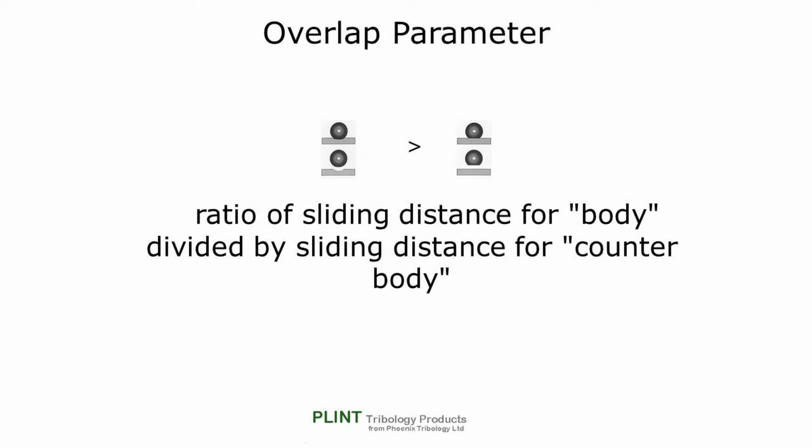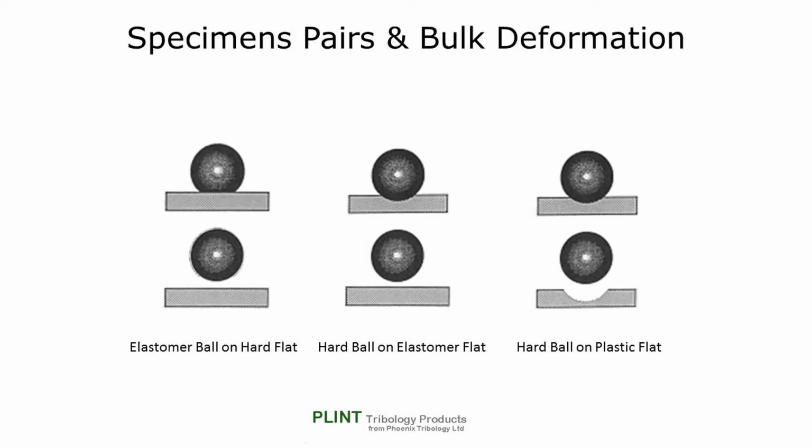The longer the stroke, the less the linear wear on the plate sample for a given amount of wear on the ball. Of course, the ball-on-flat contact geometry is not reserved exclusively for relatively hard material pairs, but has also been used with varying degrees of success for contacts involving polymers.